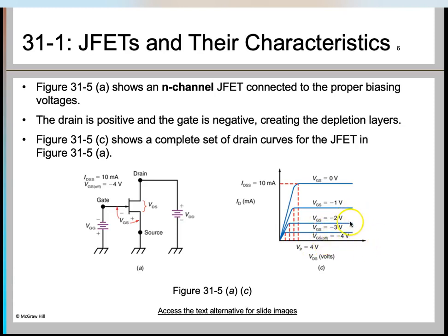And then further, it has not been shown in this characteristic, but this graph goes above like this, and that region is called your breakdown region, in which your VDS, the drain to source voltage, is high enough to cause your JFET resistance channel to break down and pass uncontrolled maximum current.